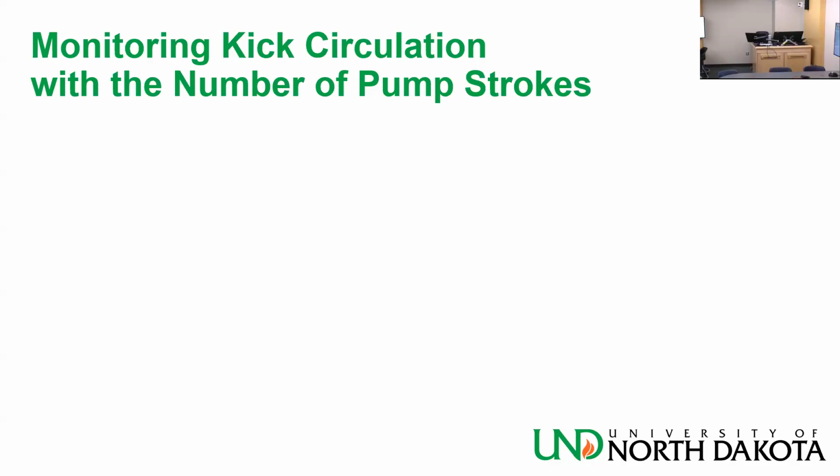So if I want 1,000 strokes to make it up the hole, I will press the reset button to 0 and start counting when I start pumping, right? 1 stroke, 2 strokes, 3 strokes. At 1,000 strokes, I know I did one whole circulation. Okay, it makes sense, right?